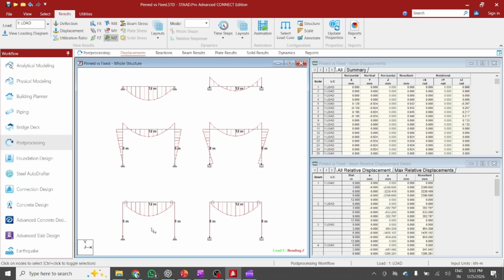Now let us concentrate on example case number 5. Here you can see for the beam, the moment is released. So the moment will not be transferred to the column. Also the column is pin supported. That means this whole structure will be unstable. The moment will not be transferred to the ground anyway.